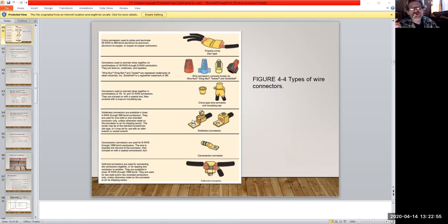And then the next one, you'll see those from time to time whenever you're required to have a tab to lock down. It's a secure way to lock it in. You'll find these sometimes in specialized panels, that kind of thing. It's a single wire crimp-on. You want to always make sure your crimp is very good, and like I say, give it a good tug test. Grab the end of the tab with your Kleins, your lineman pliers or something like that, and give it a good pull. If it'll stand a good tug like that, then you've got a good crimp. Otherwise, if it comes undone, then your crimp wasn't so good.